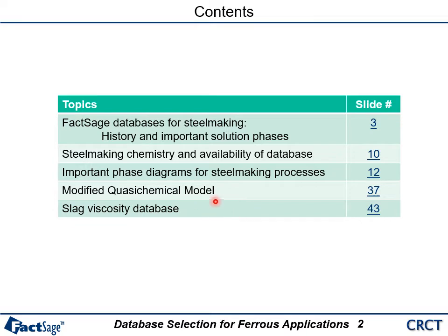And then I'll briefly show you the modified quasi-chemical model which we are using for the slag and the molten steel. And then lastly, I'll show you the viscosity model in FactSage, and how we do viscosity calculation compared to the slag structure.